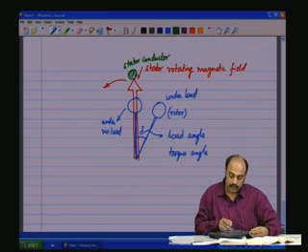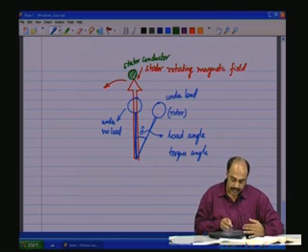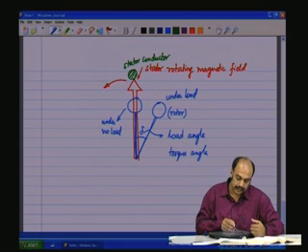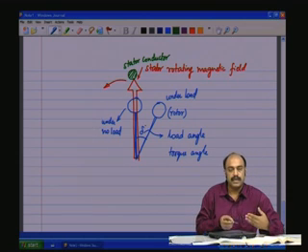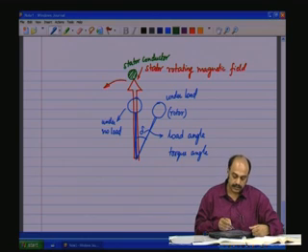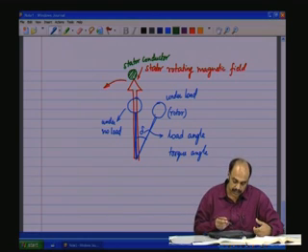The stator rotating magnetic field comes and cuts first, and then after some time the rotor field, which also has its north and south pole, comes and cuts the stator conductor after a lag, and therefore the back EMF will peak after the source voltage E has peaked, and therefore there will be an electrical lag between the source voltage E and the back EMF EB induced.